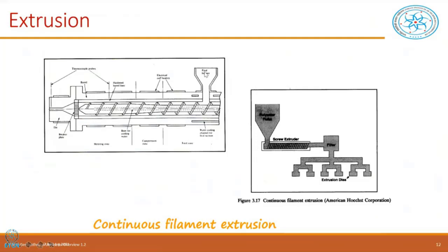That means the polymer chips are placed here, continuously heated, and then pushed out through these holes. Like we have different sizes of bhujia, or noodles, whatever you make, it all depends upon the kind of small holes we have. They come out because they are pressurized, either in the horizontal direction or the vertical direction. When it comes out, I saw a factory long ago called Petrofils in Ahmedabad itself. As it comes out, you can touch it, because it is coming out at the melting point temperature, 140 degrees, let us say.